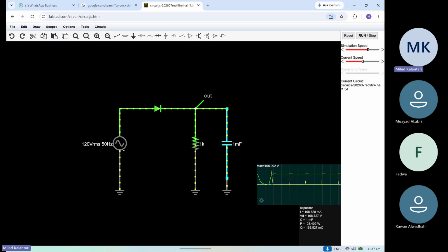But from the circuit, we can actually calculate how much this variation is, right? We know when this is fully charged, and then after a while, it is going to be discharged. We know the time constant, we know the dead time, we know all of these things. Then we can calculate how much it goes up and then discharges. And based on the requirement, let's say it should not charge or discharge too much, then we can find a value for the cap, right?